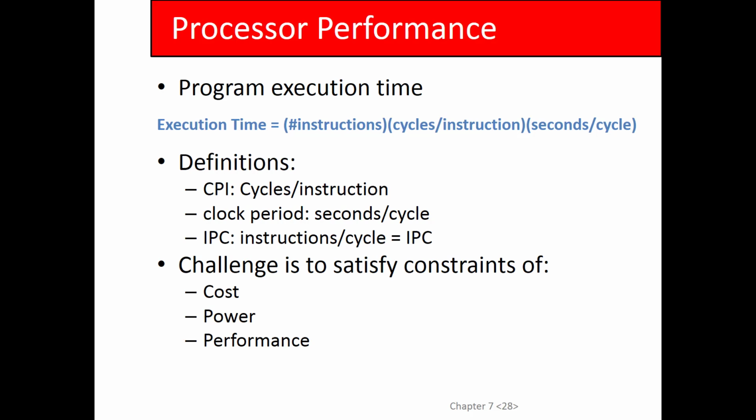And then you multiply that by the number of cycles per instruction, CPI. This is important because this term connects your program, in terms of instructions, and the microarchitecture, which operates in cycles. This is the bridge. This is cycles per instruction, the ratio that relates how many instructions you execute, which is a very abstract thing, and the actual low-level details of the digital logic design, which operates in clock cycles.